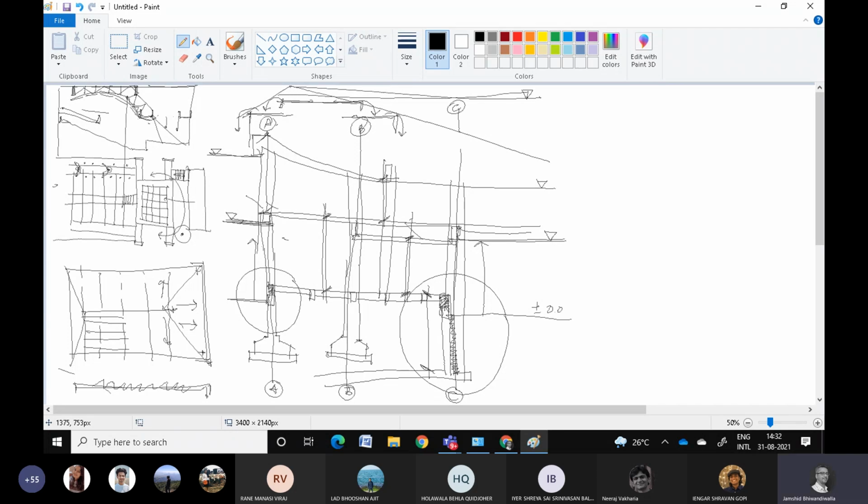But naturally the beam bottom of this slab that you are casting on the ground floor will actually say to what level the retaining wall is to be cast. The height of the retaining wall will not come right up to the floor. It will preferably stop at the level where you want to cast the beam of the slab and allow the beam of the slab to integrate or merge along with the retaining wall.